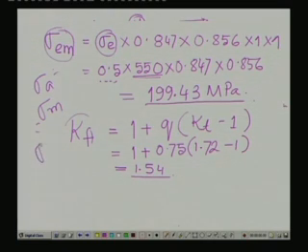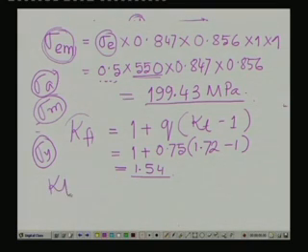You require sigma yield point, isn't it? So we require sigma yield point, sigma A, sigma m, the endurance limit for the machine member to be designed, and the fatigue stress concentration factor Kf.